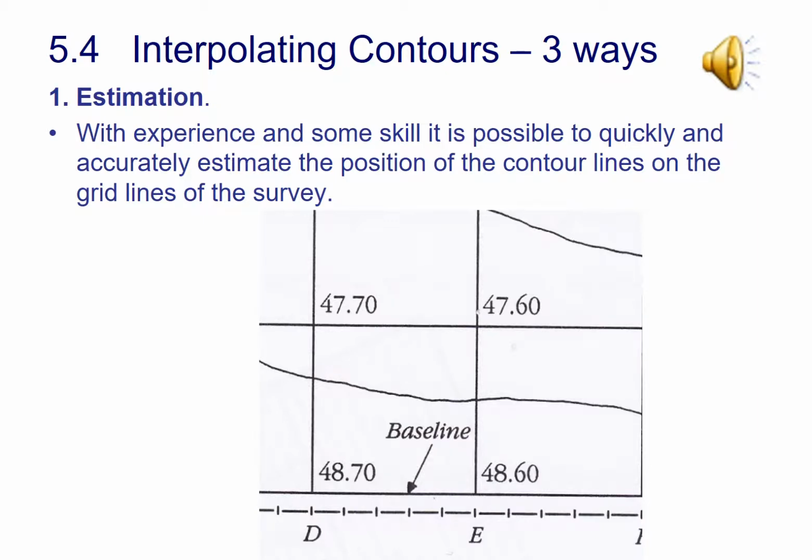So they're not too far away. And that's why you'll see the person has drawn the contour line approximately halfway between the two, although closer to 47.60. So that's with estimation. As I say, I wouldn't recommend it. It's just a good idea to check that you're not far off the mark.